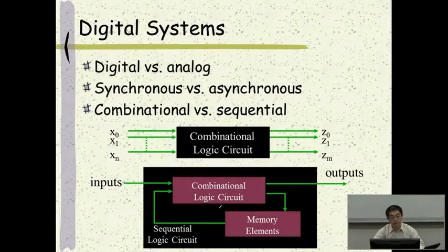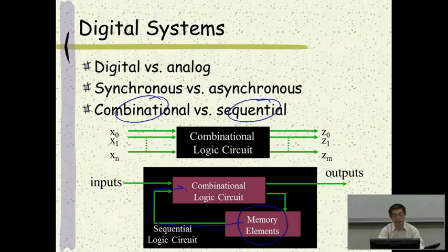We have seen these slides earlier. This one tells the difference between the combinational logic and the sequential logic. And we mentioned the key differences. In a sequential circuit, there's a memory unit, which stores the current contents of the system. And this current content of the system will come back here, affect the combinational logic, which is going to eventually impact the output. So the output not only depends on the input, it also depends on the memory unit.